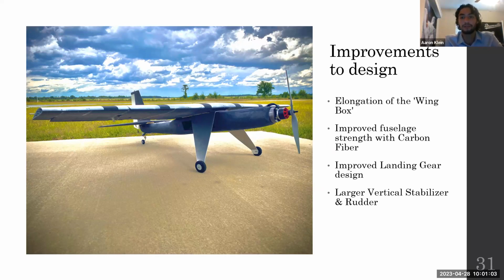The landing gear was made from a single piece of sheet metal as opposed to being made from two separate struts like before, which improved the alignment and strength of the part. Making the landing gear out of one piece of sheet metal also allowed us to move the mounting location to a much more favorable position. The landing gear was mounted between the wing and fuselage on top of the plane, with the fasteners of the wing running through the landing gear plate securing it in place.